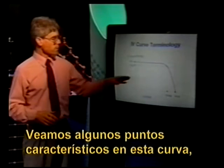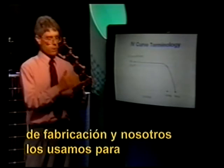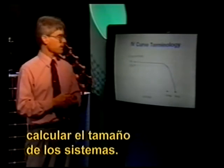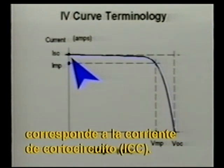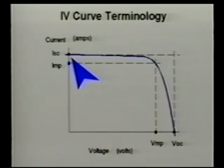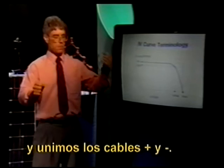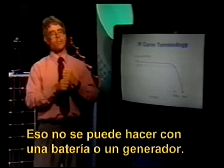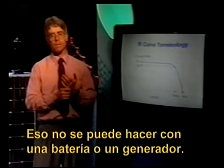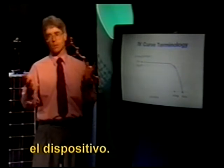Let's look at some characteristic points on this curve, because they're always indicated in all manufacturers' literature, and we use them in our system sizing calculation. If we begin in the upper left-hand corner, that point corresponds to what we call the short circuit current, ISC. What do we mean by that? We mean that effectively you've taken a module and put the plus and minus wires together. You've shorted the module. Now you can't do that with a battery or a generator. It's dangerous. Extremely high currents flow, and the device is actually damaged or could blow up.